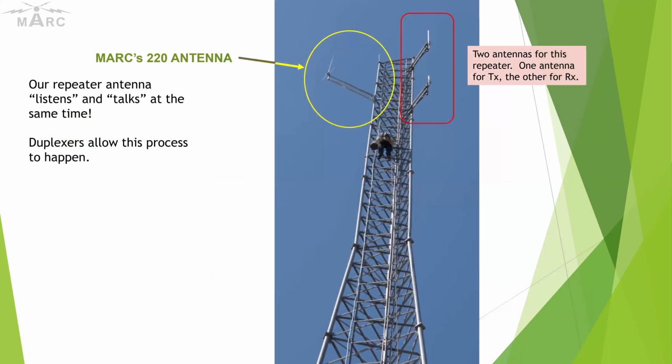Now, let's take a look at the Mark 220 antenna. You can see it's a single antenna. There's like an 8-foot LMR 400, and then it's 7/8 inch heliax all the way down right into the lightning arrestor.